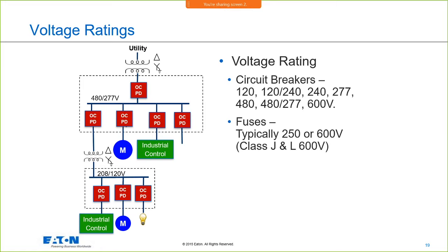For example, if you have a slash rated device in one plant that's a grounded system, but you have an open delta or a corner grounded delta system in another plant, and you want to take that same piece of slash rated equipment and use it over there, you can't because you might be exceeding the voltage ratings.